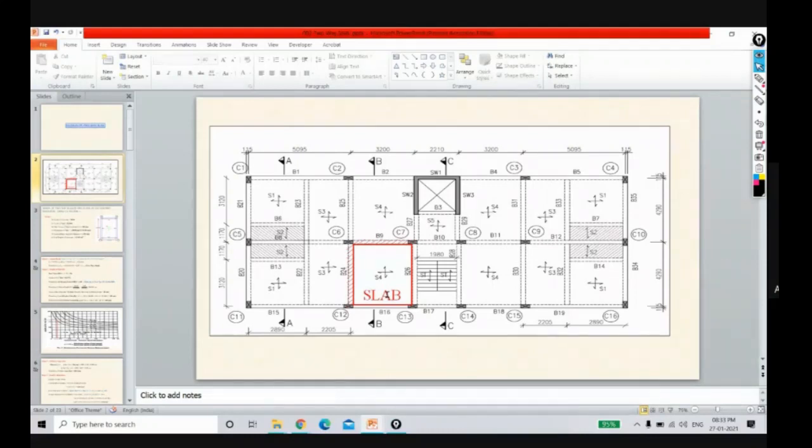So first we have to design it, then check your reinforcement against the existing reinforcement, and then decide, or depth also, then decide what defects are actually there. Maybe some defects are in the concrete also. Correct. So whatever concrete is required at that site, suppose M20 grade of concrete is required and they have provided M10 or M15, then that concrete is not sufficient. That we have to do in the structural auditing.